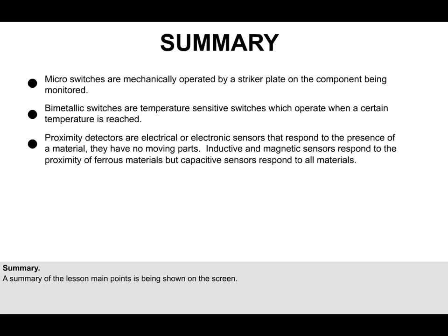Proximity detectors are electrical or electronic sensors that respond to the presence of a material. They have no moving parts. Inductive and magnetic sensors respond to the proximity of ferrous materials, but capacitive sensors respond to all materials.